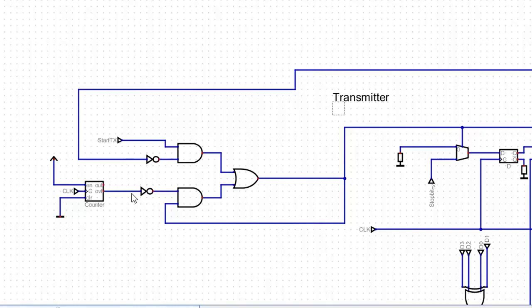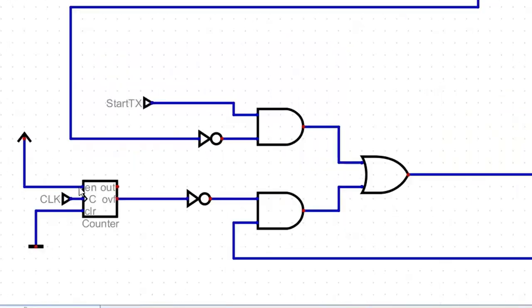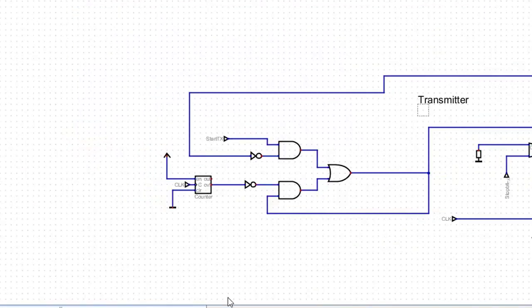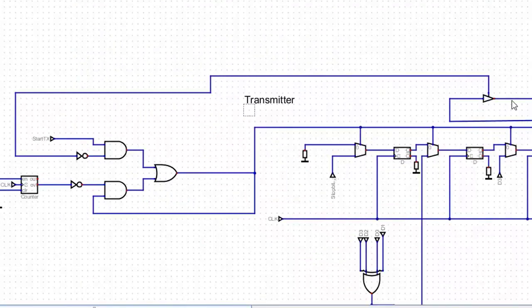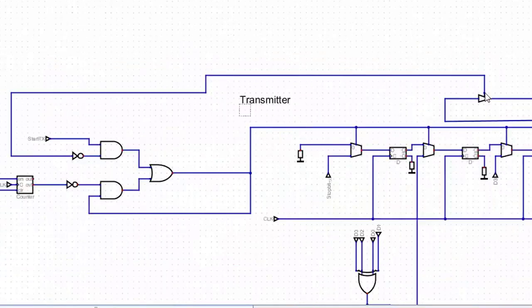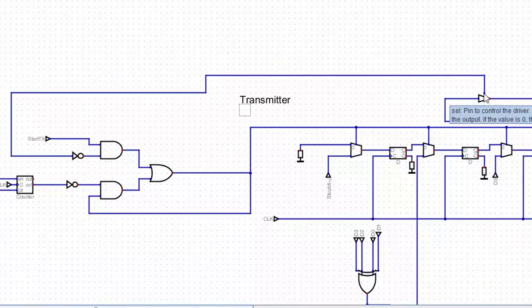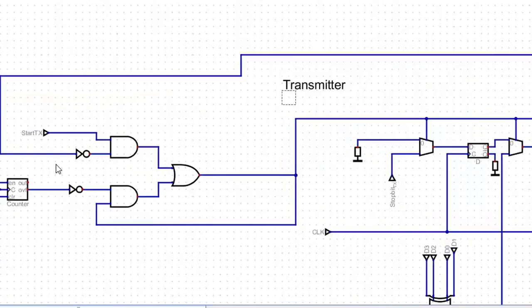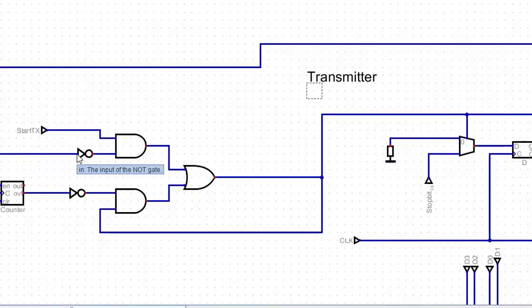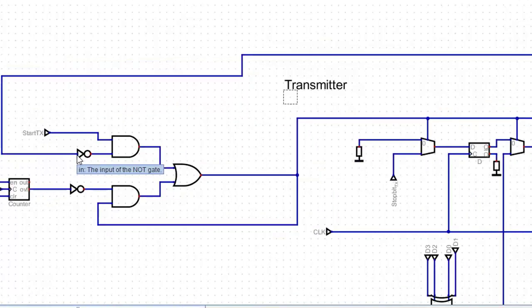The buffer that you have on the right. Just point to the output enable line on the tri-state buffer. Just hover above the output enable. Do you agree that this output enable line is an input into the tri-state buffer? Yes. Okay, just go to the inverter that's connected to that. Do you agree that that point there is an input to the inverter? Yes. So do you agree that you're driving two inputs against each other?